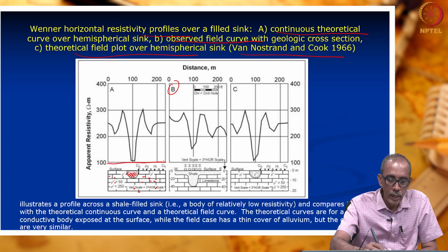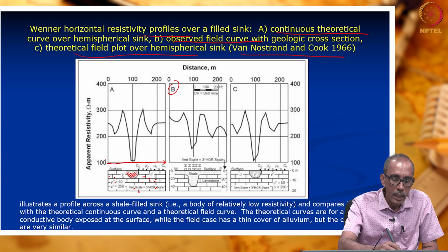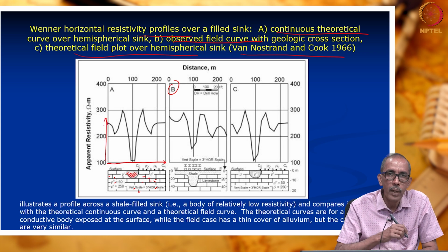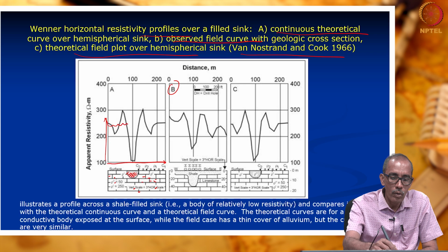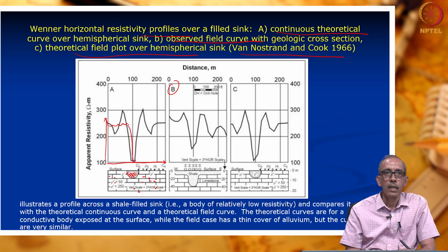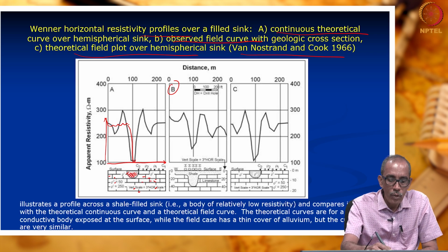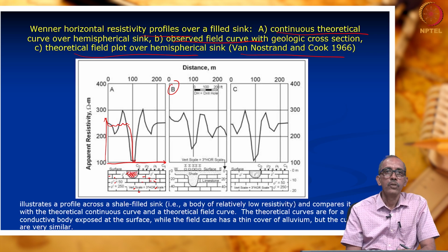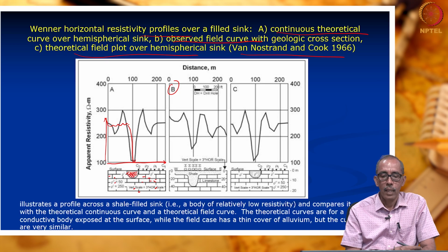So, this is the profile we have investigated. Here you can see this is the variation in the apparent resistivity. Apparent resistivity was hovering here, just above this sink the resistivity has dropped down. So, we are able to clearly bring out the reduction in the resistivity indicating the presence of a low resistivity zone at the center.